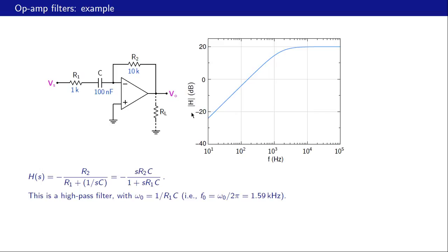Let us change the frequency from, let's say, 10⁻⁴ Hertz to 10⁻² Hertz. That means we are going up in frequency by a decade, and as a result we are going from this mod of H to this mod of H, and that is 20 dB. So the slope is indeed 20 dB per decade. Here is the SPICE file. You can play with these parameters, the component values, figure out what this plot should look like, and then run the simulation and check whether your prediction is correct.